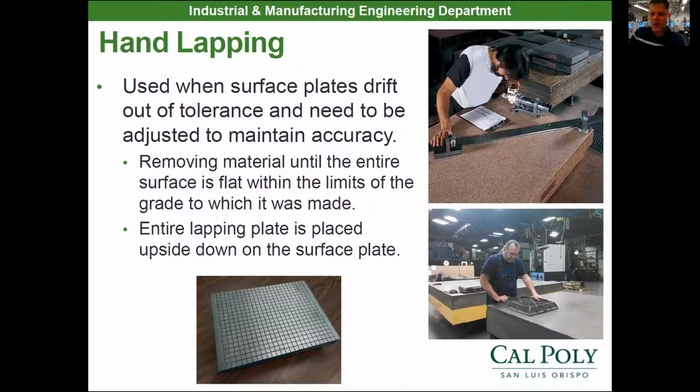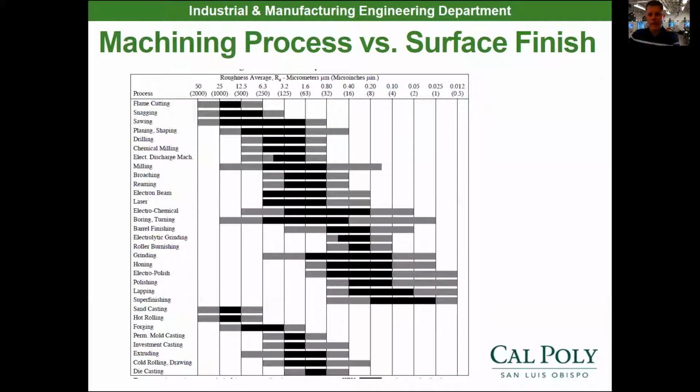I found some pictures of them reconditioning surface plates. So when your surface plate needs to get calibrated, someone actually comes into the shop because of how heavy they are. So you have the person come into the shop, they measure the surface plate, they again basically relap it, they remeasure it, it gets a first article inspection on that surface plate. Now it's qualified to be able to measure in the aerospace industry or the automotive industry. So you've got to get your stuff calibrated. You've got to have a calibration record if you expect to be an ISO 9000 certified shop out there.